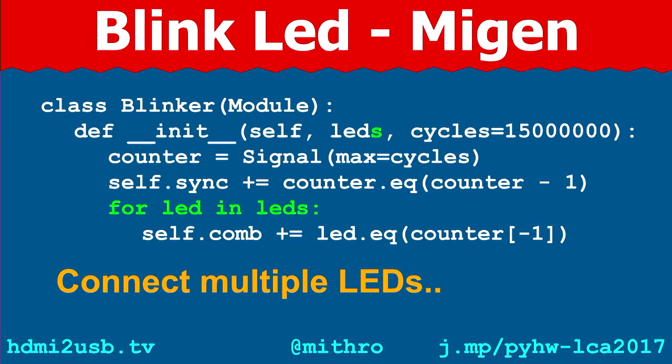And this is really, really powerful as well, because you can do if statements in your code which generate different code depending on your settings. And then the compiler that's taking the Verilog and converting it to the FPGA code doesn't need to try and figure out that you didn't actually need these things, because these things were never in the code it was looking at. So it can also be much more efficient.